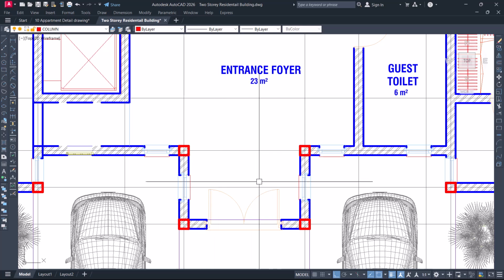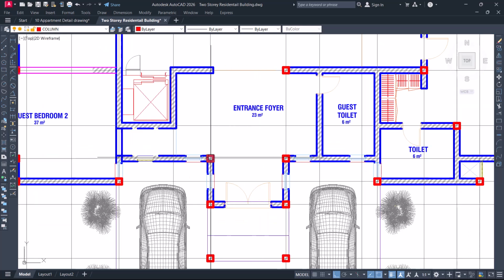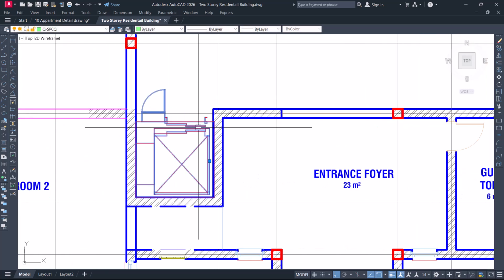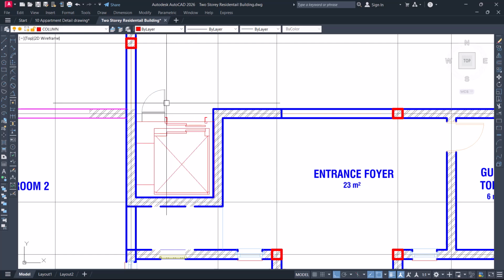Yeah, but even at that, I still want to have my beam cross this. But I can still choose to leave it actually, to have just the beam crossing this place. So let me just cross this with a beam first. Cross this with a beam here, a beam here. Let me explode my lift so that I can be able to see it when I export it. I'll explode it and X enter. Okay, that's fine.